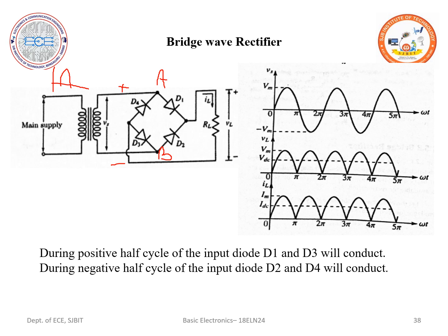Now once this is going to become positive, point A is positive now, can I not say my diode D1 is now in the forward bias condition? Look into the diode D2. Is it in the forward bias? No, this is because it is a reverse bias.